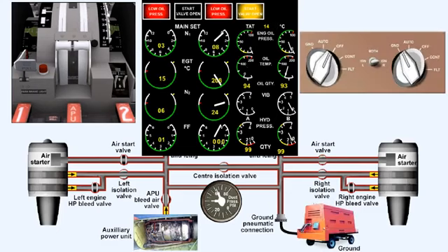It's really only possible to determine that a hot start is happening by comparing its indications to those of a normal start. The EGT may initially rise as normal, but then a rapid rise towards the engine's EGT limit, caused by a hot start, will become apparent a few seconds after light-up.